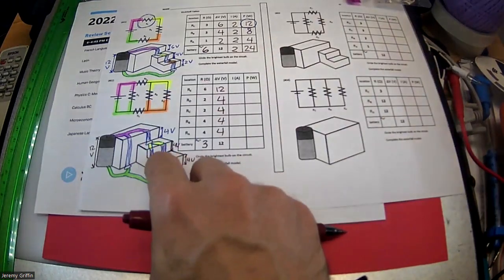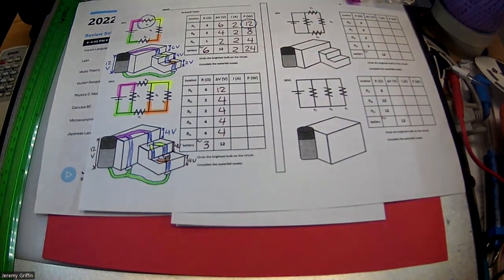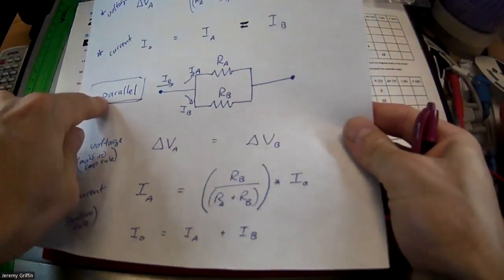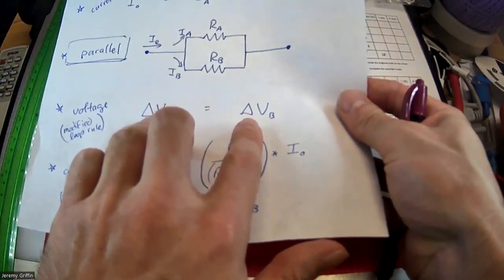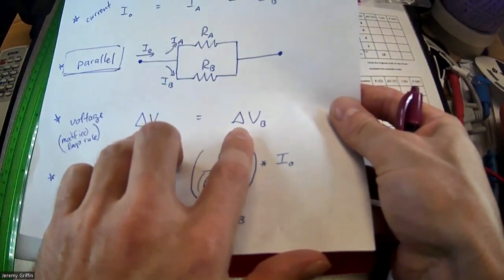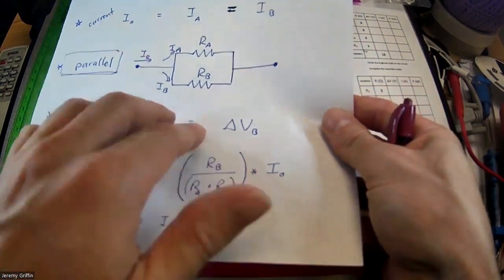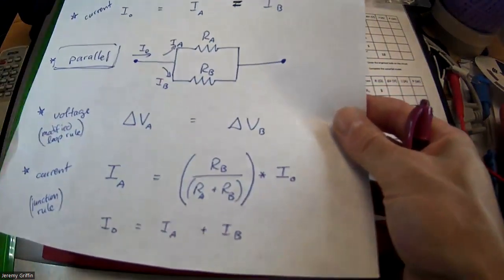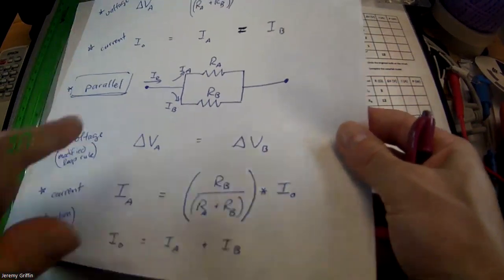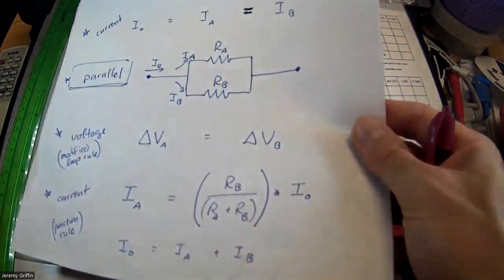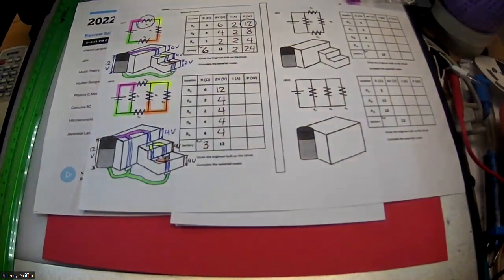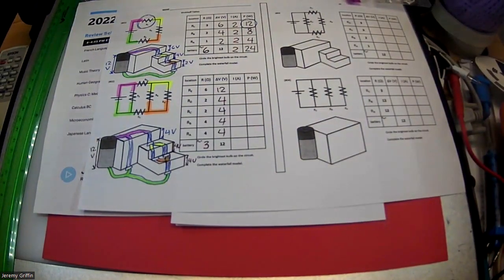Well, except of course you don't want to double count the 2 that are in parallel, because resistors in parallel, like A and B, have to have the same voltage drop. You remember that? It's a rule. It doesn't matter if they're wildly different resistances or not. They might be the same resistance. They might be like 1 ohm versus 99 ohms. It's going to be the same potential difference. It's just a rule of electricity. You got that?